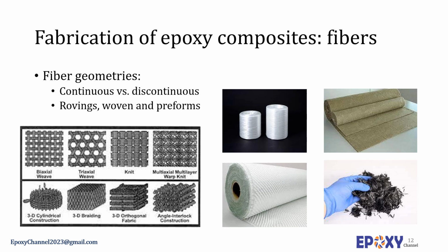Fibers of similar length are incorporated into pre-impregnated sheet known as sheet molding compounds or SMC. In SMC, the fibers can be present in various geometries. SMC employs thickened resins but with a wide range of epoxy resins. Often prepreg technology is employed. For epoxy resins, the predominant fabrication process incorporates continuous carbon, aramid or glass fibers, and the technique involves rolling directly as woven cloth or as preforms.